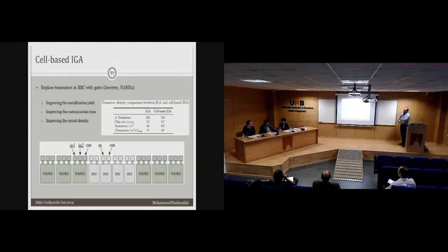I see. So you don't anticipate doing cell-based on the all-inkjet then? Photolithography. I see. Okay. And looking forward now, you mentioned SPICE modelling or analog modelling of some sort. Have you looked into which OTFT or silicon-based SPICE model you might be using? Have you had any ideas on that yet?